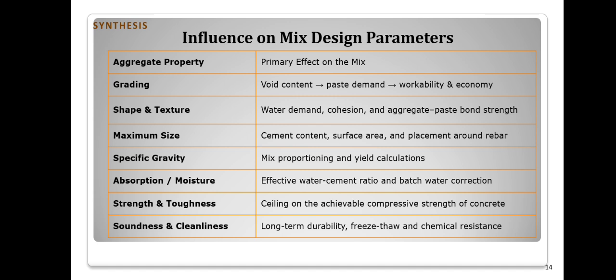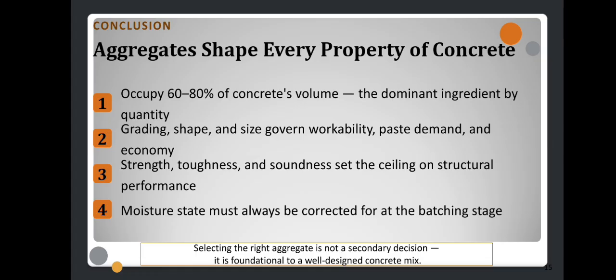So to conclude, aggregates are not merely fillers. They occupy the largest volume in concrete and influence the strength, workability, durability, and cost of the concrete. Proper selection of aggregate, grading, size, shape, moisture condition, and quality is essential for producing a durable and economical concrete mix. In short, good concrete begins with good aggregates.